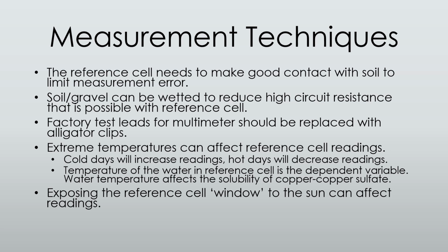And exposing the reference cell window, so there is a window that you can look at your liquid inside, see if it's clear or not. If that's in the sun, it will also affect your readings on your reference cell.